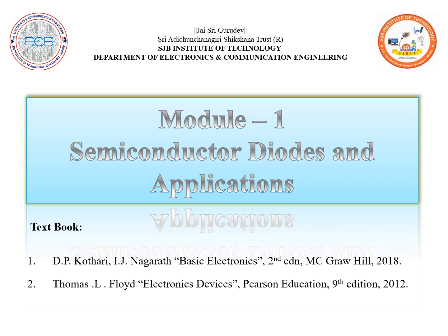Ripple is nothing but some amount of AC component which is present in the DC output of the rectifier. We call it a ripple, right? So whatever ripples are present in the DC component at the output of the rectifier are going to be removed and we get the pure DC.